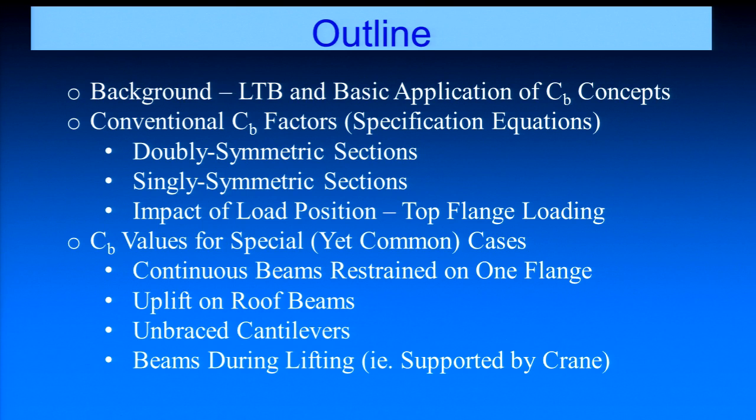As far as the conventional C sub B expressions, we're going to look at what we do on doubly symmetric shapes. We'll talk a little bit about whether we have to make any changes for singly symmetric sections. We're going to talk a little bit about the impact of load position and try to understand what we mean by that, because a lot of times transverse loads may be applied at a variety of different locations: top flange, mid-height, or bottom flange of the system.